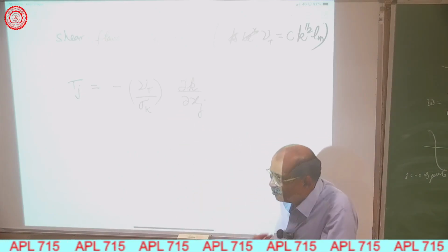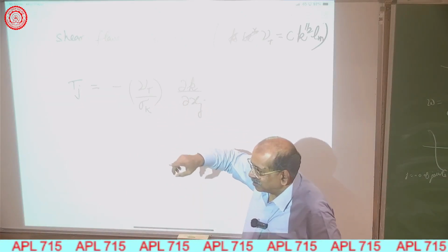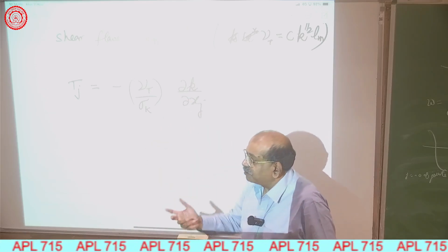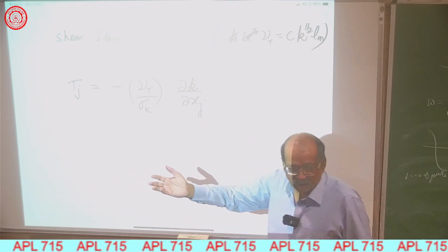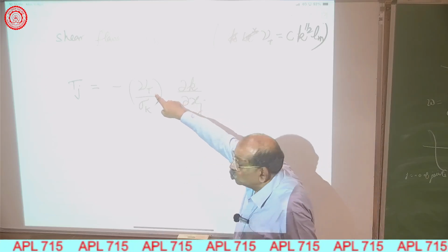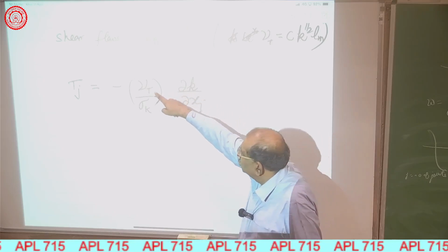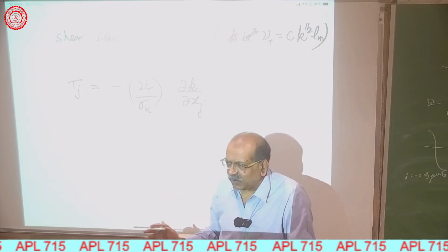Because once again this follows, if you write the heat transfer equation and you write nu, then you say nu divided by a Prandtl number. That is what makes it alpha. So that's why we write it, nu was actually for the mean velocity. So we write it as nu T divided by sigma K. Normally sigma K will be taken as 1.